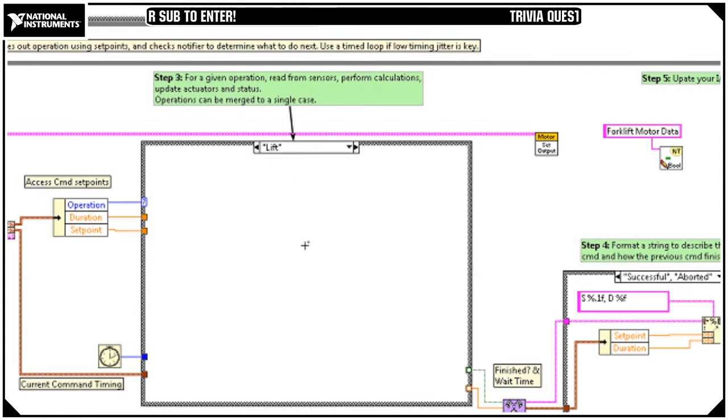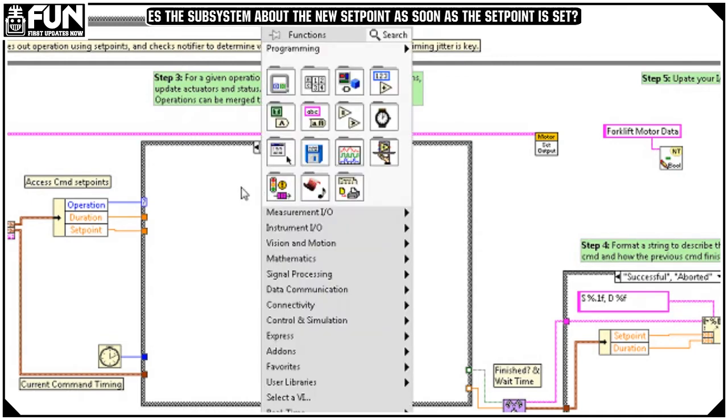So looking at our 2 cases that we've added, lift and climb, if we're lifting, we're saying this is us picking up the power cube. Probably when we're doing this, we don't want our motors going super fast, right? I don't want a full joystick and the power cube just flies off into the air. That would be terrible. So we're going to add a slight reduction to our motor speed here.